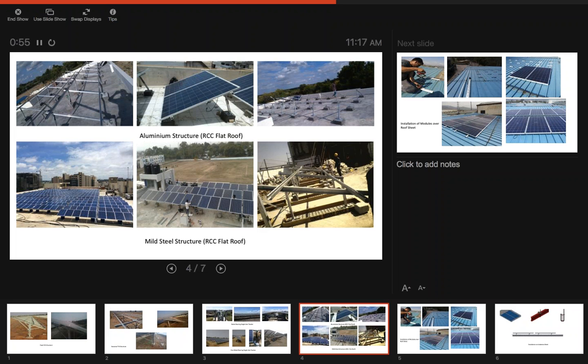Satish, can you tell me how we size these foundations? What are the criteria when we are doing an in situ foundation? Based on the structure uplift, like the support reactions from the structure, and based on the wind speed, we will get the uplift capacity. Based on that, we know that concrete has a unit weight of 25 kilonewton per meter cube.